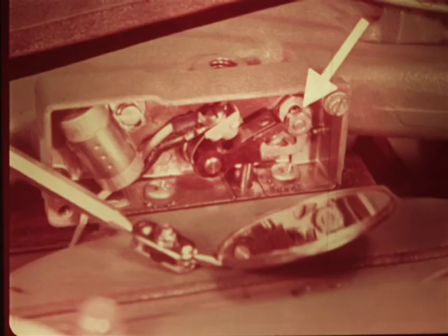If an adjustment is necessary, use a small hand mirror behind the breaker box to see what you're doing. Use a short-handled screwdriver and ignition wrench to adjust the points so the timing is right.